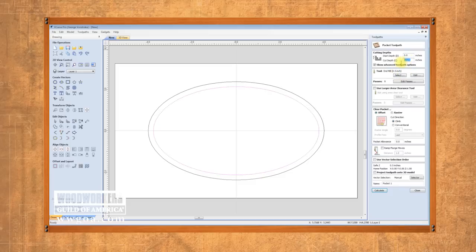And then here we can set the depth of cut. So let's think about this. We've got a 1 1/4 box. This is currently set for a 1 1/8 depth of cut. That's going to work out just fine. Working my way down here. This is a good thing to look at: this raster option would move the bit back and forth in the same direction as the grain of the material. Maybe it gives you a little bit better surface finish. This is going to move just like the lines on here show it. That's going to take material out a little bit more quickly. I'm going to go with the more quick material removal.